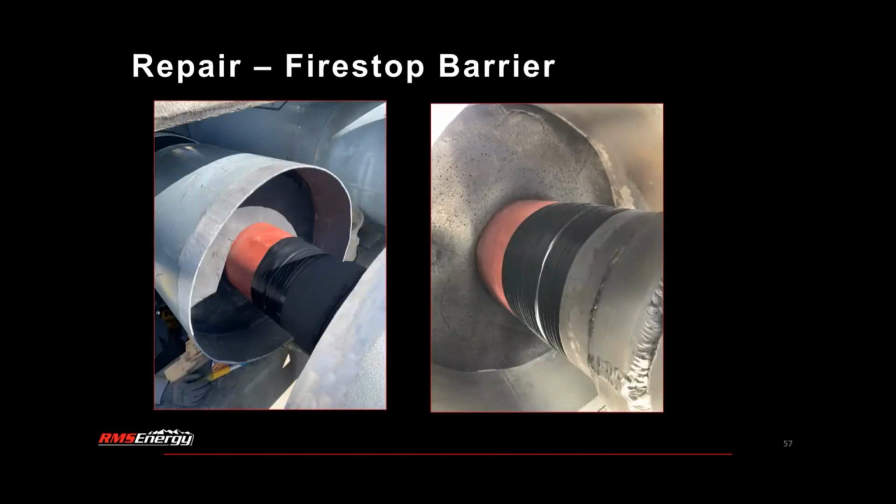So we went ahead with repair and replacement of the unit. We replaced all three phases, the fire stop material, on site. So we used a new fire stop or fire retardant foam that was used in another manufacturer's design, and replaced the insulation on the conductor and returned this unit to service.